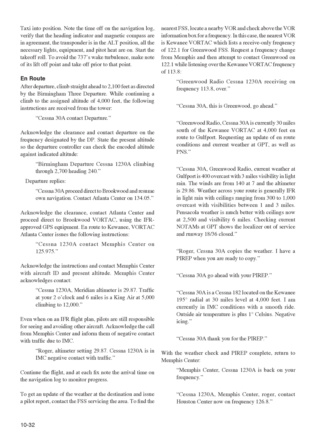Acknowledge the call from Memphis Center and inform them of negative contact with traffic due to IMC. Roger, altimeter setting 29.87. Cessna 1230A is in IMC, negative contact with traffic. Continue the flight, and at each fix note the arrival time on the navigation log to monitor progress.